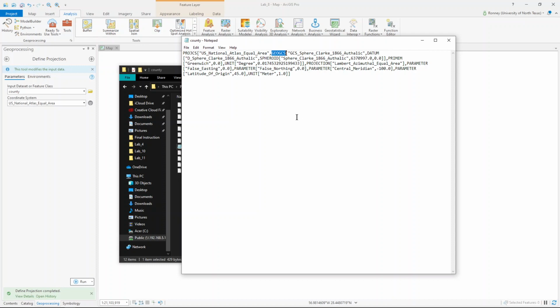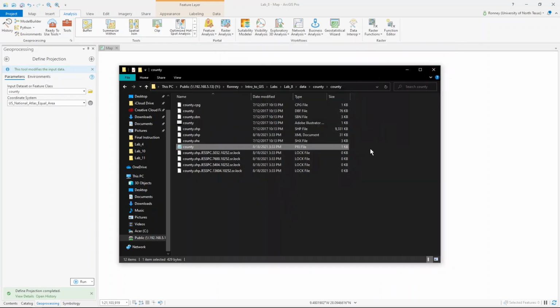And that's usually without going into ArcGIS Pro and opening everything up and examining everything. That's just what I'll do is I'll open it up in Notepad and check the projection on it first. And if you plan to go into GIS and use GIS as a tool, or you plan to be an actual GIS analyst, that's something that will become handy in the future.